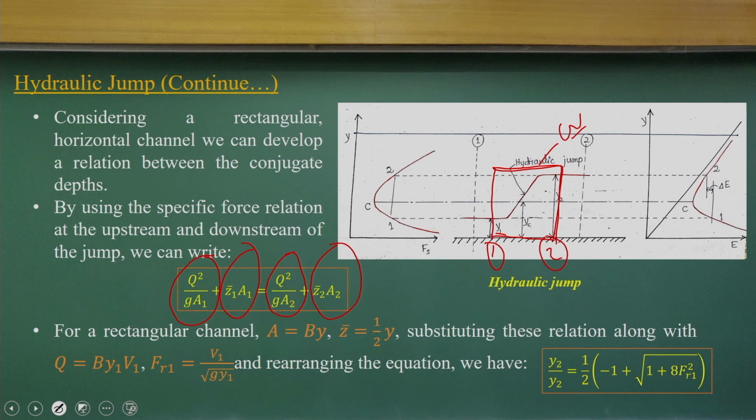That means, for this control volume where the hydraulic jump happens, we apply the linear momentum equation. As we consider there is no significant frictional force acting on this short reach, we can write the force terms in the linear momentum equation in terms of two components: the linear momentum flux component per unit weight and the pressure force component per unit weight.